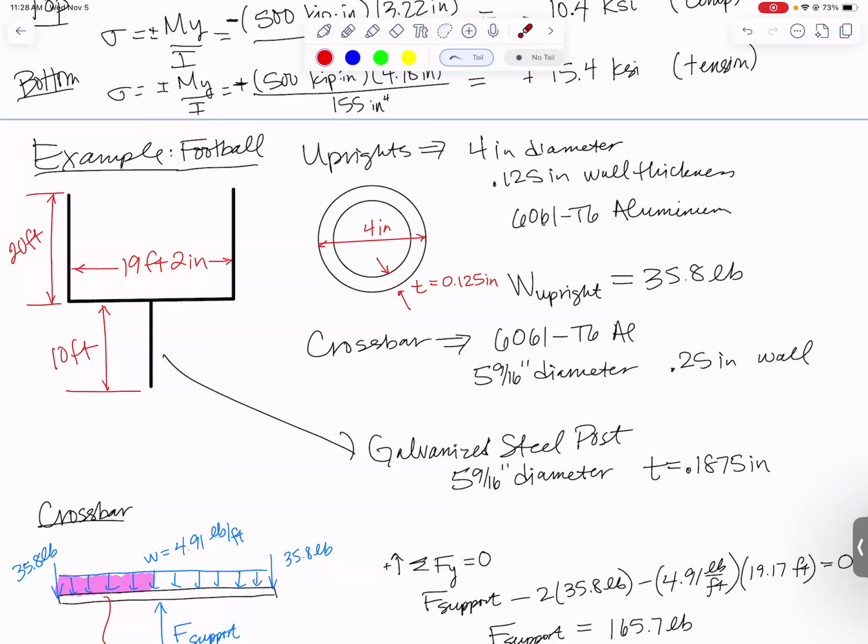Typically what happens is that the hollow cross sections actually start to crimp and crush. And that is related to a kind of buckling instability that, again, is beyond the scope of what we can do in our class, and also will tend to cause things to fail at a much lower load. Four things tend to cause this to fail sooner than our analysis would predict.